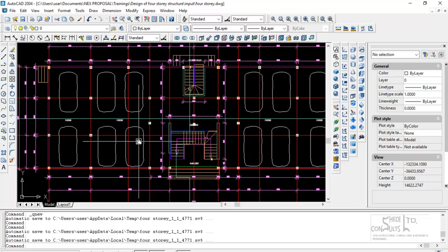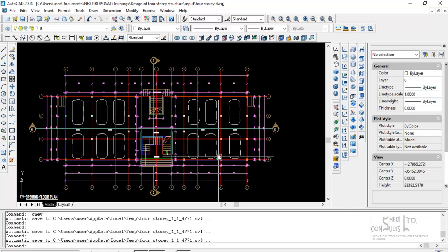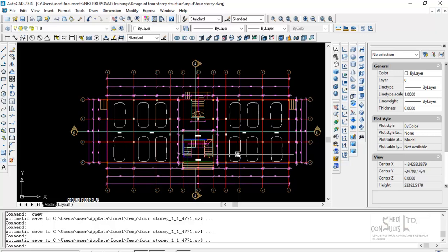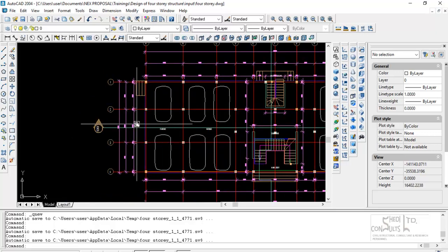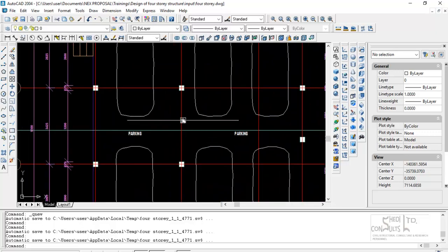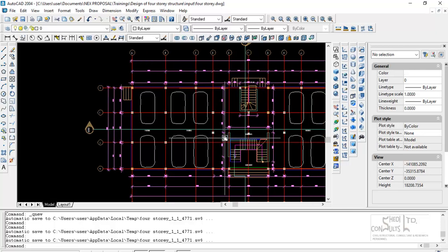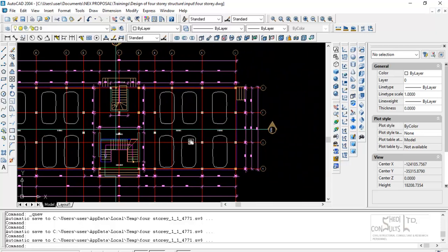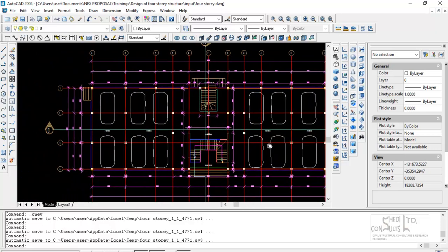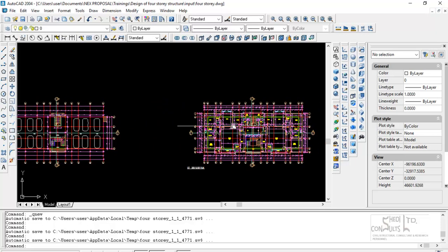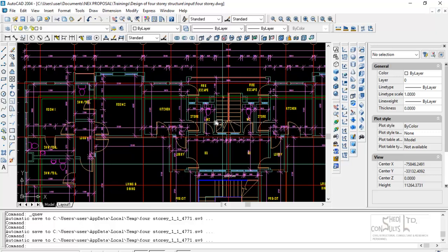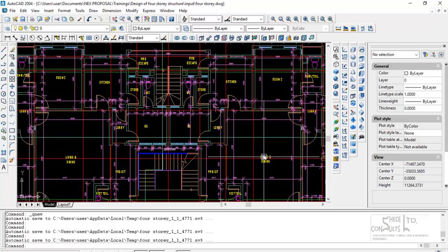stratum. So you need to study the subsurface investigation reports. Typical tests carried out on site are the trial pit, the Dutch cone penetration test, and the standard penetration test, together with borehole logging. The Dutch cone penetration test is a continuous testing approach where a standard penetrometer is sent down with a rig. The penetrometer is driven at 2 centimeters per second, and from the cone tip it records the penetration resistance of the soil stratum.